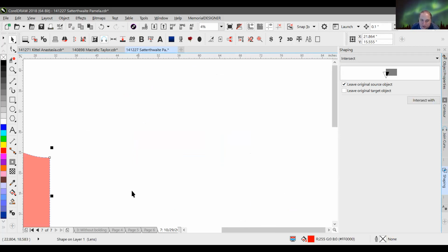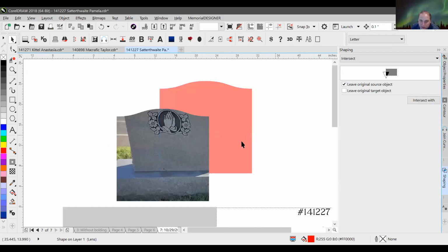Thank you. That skips you from having to go in and out of Photo-Paint as well, because you can just do the bitmap conversion right there inside of CorelDRAW. Yeah, I do that quite a bit. If I've got a bitmap that I want to freeze in a certain state, with things applied to it, I'll just convert it to a bitmap again. Even though it is a bitmap, it seems redundant, right? You're converting a bitmap to a bitmap. But by doing that, you're flattening all of those effects so that there are no effects applied to it anymore.